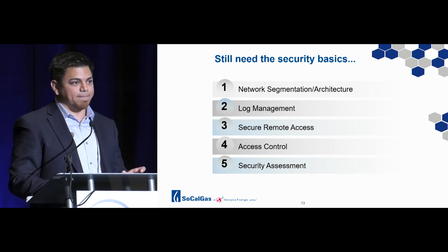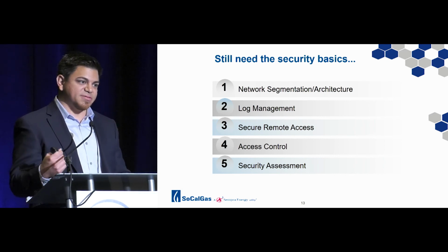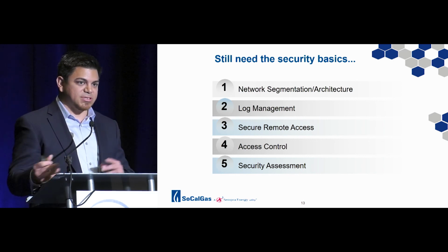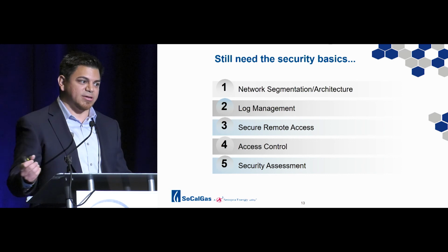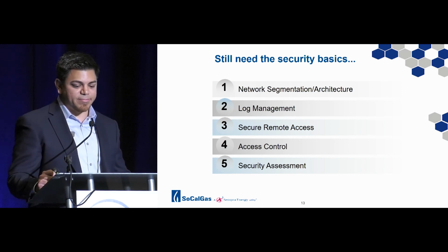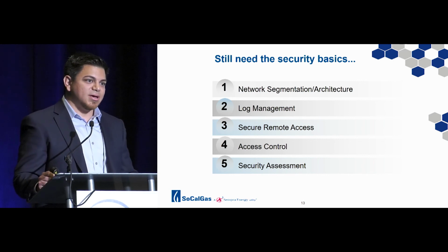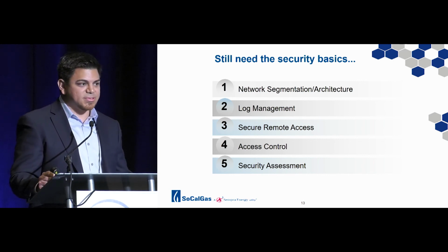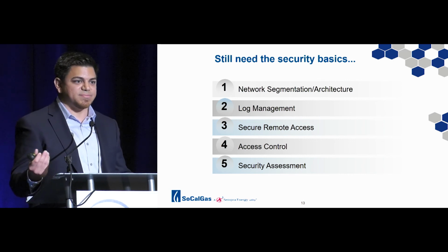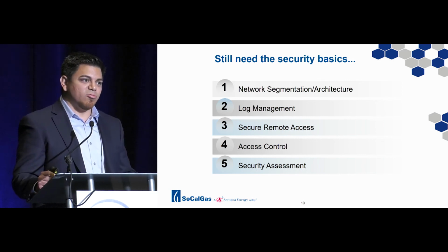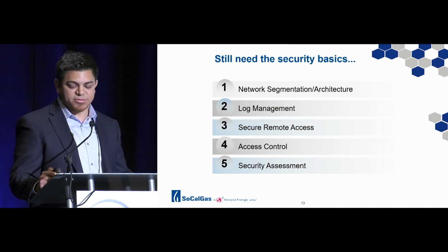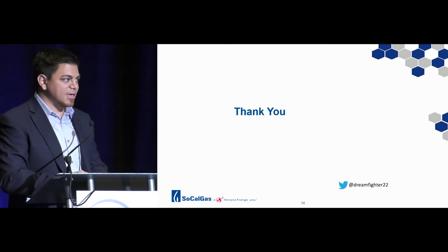We hold the token that's dynamically generated. So when the automation vendor wants to remote in, they have credentials, but they still need the token. So we can still have some control and understand when vendors are accessing our environment. Access control, not using default credentials. And finally, security assessment, really understanding what assets you have, what vulnerabilities they have, and how you can mitigate against those vulnerabilities. And thank you.